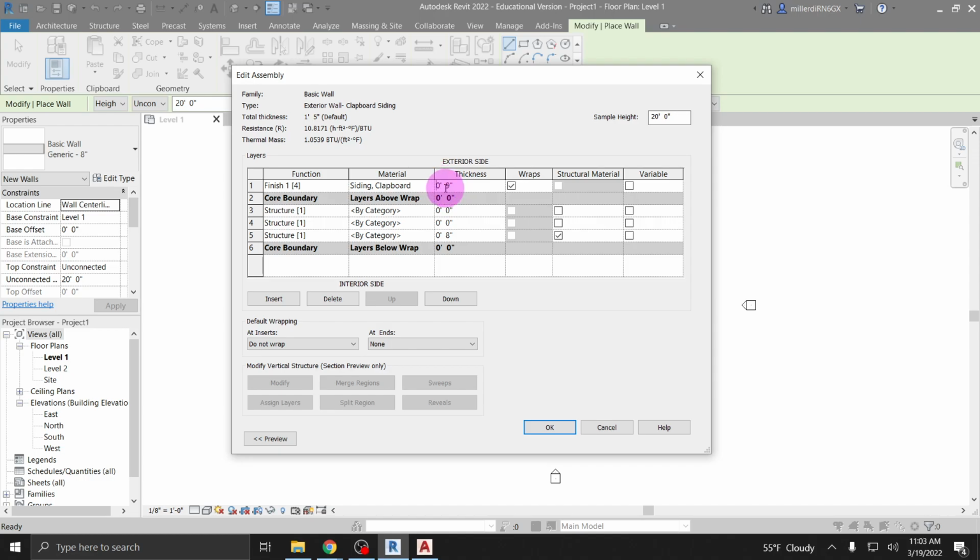You don't have to put this foot designator and this inch designator, but if you're doing something in only inches, you still do have to put a 0 just to represent that there's 0 feet. And then I could type in 3/4. And now it's going to give this material a thickness of 3/4 of an inch. Then next up, so now we have this first layer of the wall done. Again, I know this is a lot, but it's worth it to apply all of this stuff beforehand.